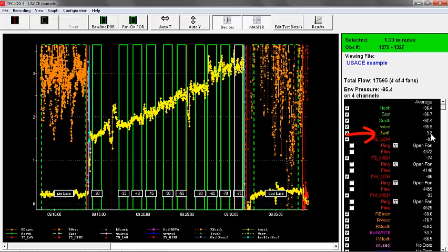So again, less than 5% of our induced pressure. So we're well within that 10% standard. Even though we only have fans on 1 floor on a 10-story building, we're able to achieve good results and good data on the test.